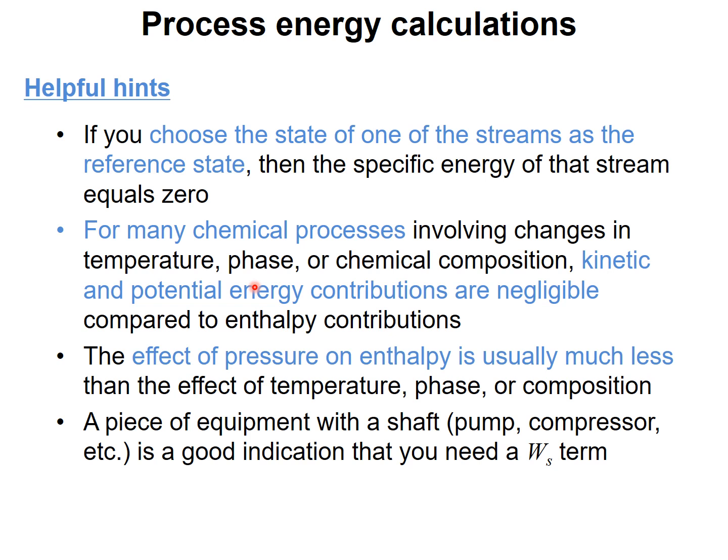You will focus on the enthalpy flow on the right side of the energy balance equations. Also, even in the accumulation term, you will focus on the internal energy. Please neglect the kinetic and potential energy for chemical processes. The effect of pressure on enthalpy is usually much less than the effect of temperature, phase, or composition.